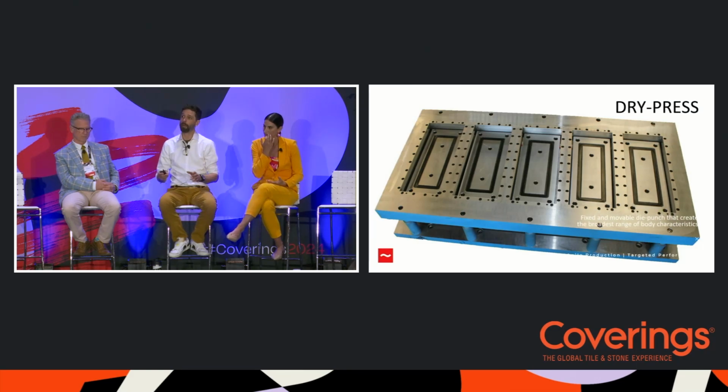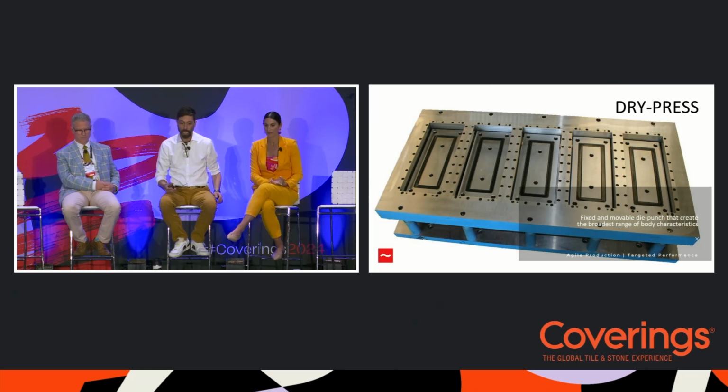I'm starting with dry press because this is probably 70 to 80% of the tile that you see on the floor here at the fair. It's the broadest range of tile production that we do. And basically, this is a punch. It's a stainless steel punch that these rubber impression molds go in. One side of the punch moves down to accept the clay, and the other side punches it and pushes all the air out and presses it into the shape. And then that gets pushed out and moves on down the line and continues.